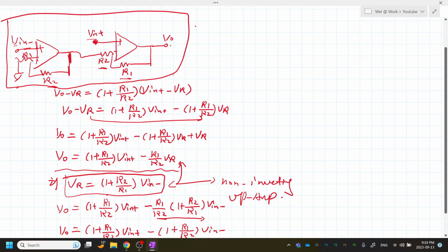This has a lot of benefits compared to the typical four-resistor, one op-amp difference amplifier we talked about in video number 9, I believe. And the most important property is that we now have a high impedance input for both V in plus and V in minus. We could talk about some examples later on why this is important. This input goes directly into the op-amp. Ideally, with the ideal op-amp, you have infinite input impedance. This is very important in some circuitry.